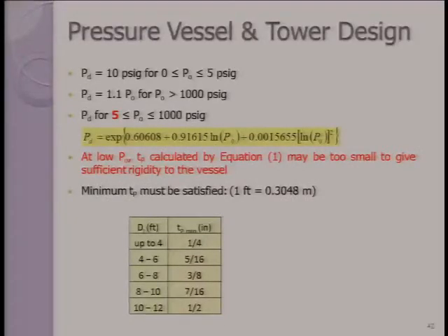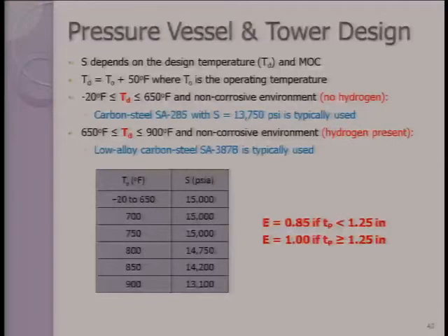The next step will be to calculate the maximum allowable stress. The maximum allowable stress depends on the design temperature now, not the operating pressure. The design temperature is defined as the operating temperature plus 50 degrees Fahrenheit. So that's TD.